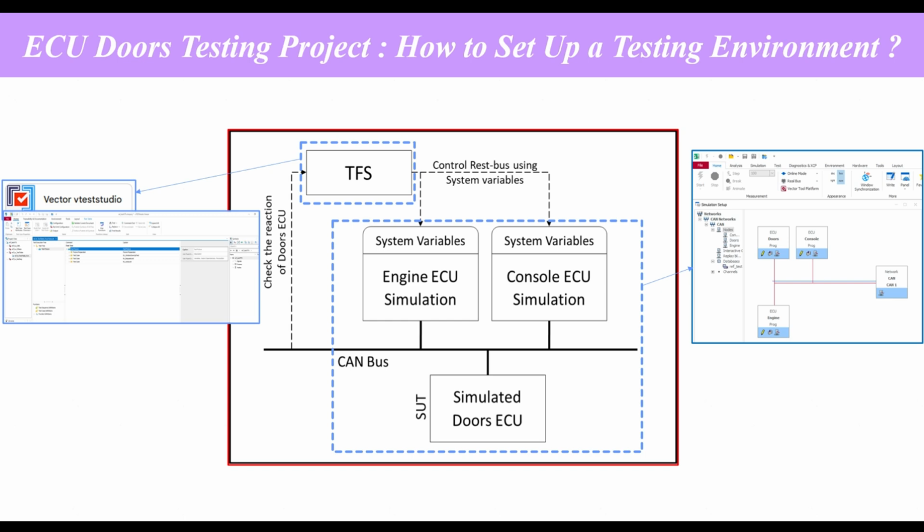Usually, once the test plan is confirmed and defined, the next step is to prepare the setup of testing. If you are in the lab, you should prepare all the tools that you will need to do your testing. For example, you can prepare the harness, your power supply, tools like an oscilloscope, and other tools.